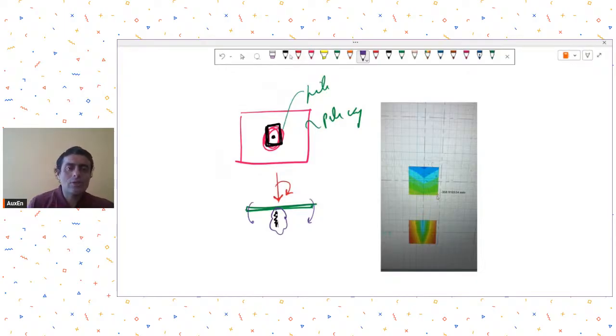So as long as your loads were perfectly axial in the column and completely concentric with the pile below, you won't face this problem. But as soon as you have any moment in the column, or for that matter any shear in the column, then you will get unrestrained deflections.